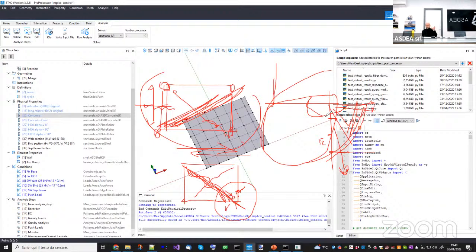So basically, what physically was happening is that a tensile crack was actually inducing crushing inside the material point. Okay, so that's why we decided to open the surface here, not to let the compressive surface be affected by tensile surfaces like this. Okay.